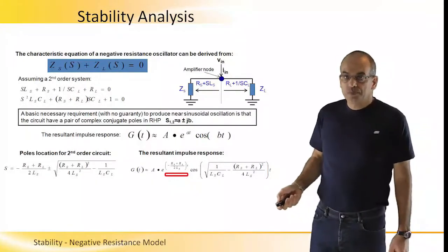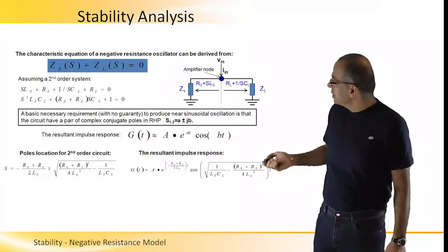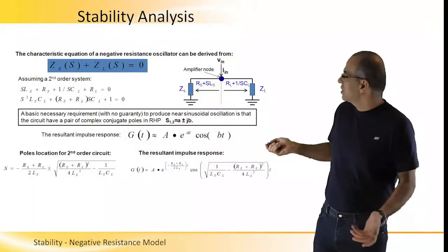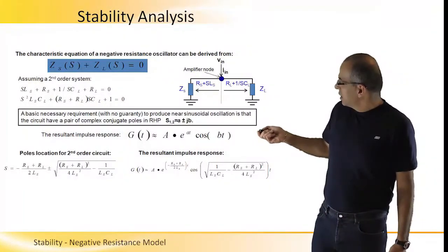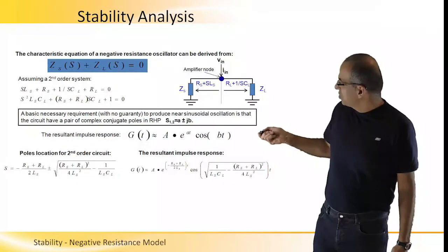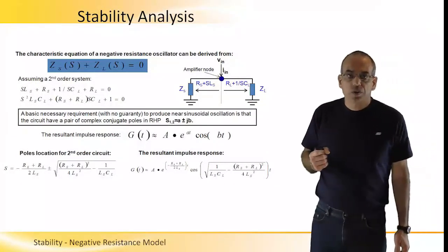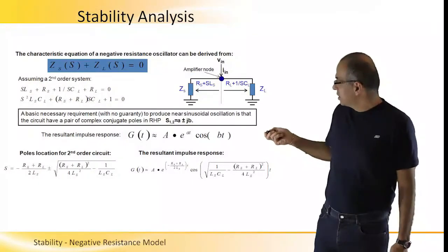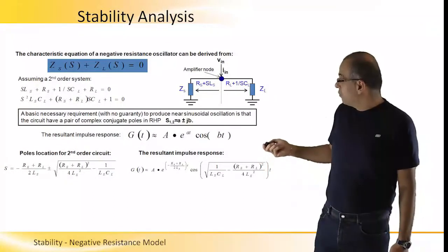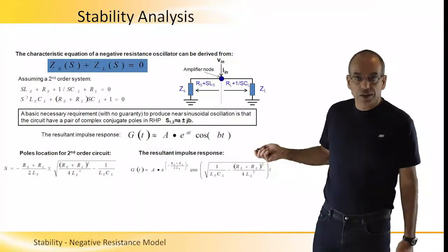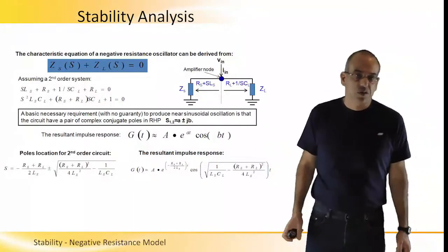So we just need to make sure that the sum will not be negative, as we mentioned before, and this explains the condition we showed before. Again, we can put these poles into this expression of the impulse response, and find out that the resistances should be positive for not getting oscillations. If they're negative, we will get this behavior and we will get an unstable system.